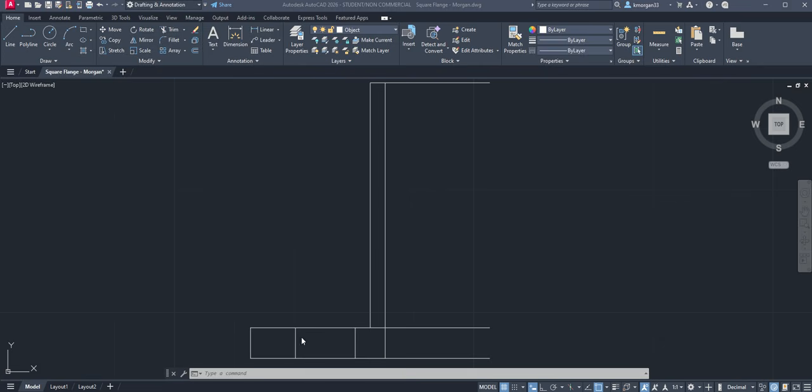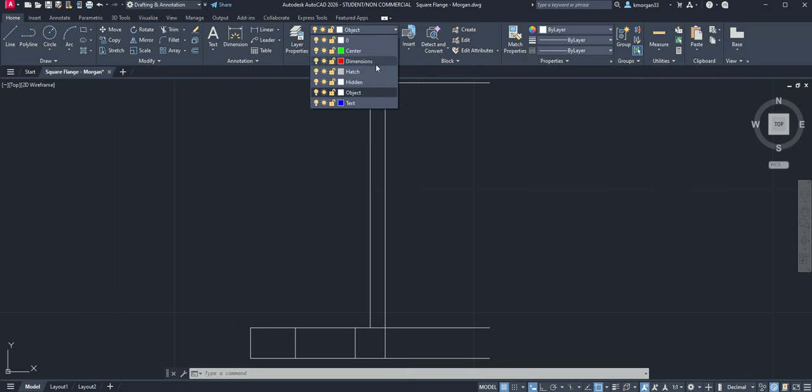After selecting a line, if you want to come back out of it, all you have to do is click Escape. Now you will go to the Home tab, and then go to the layers. We want to change the layer to hidden line, because we want to use the hidden line instead of the visible line. Save it. Now the layer has changed and we moved from the object to hidden.